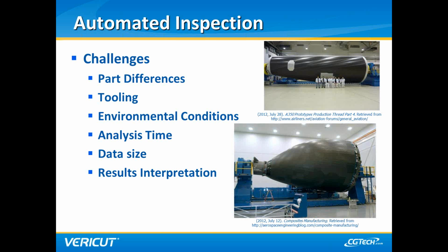And then the other one is results interpretation. So, how do you interpret results if you're looking at point clouds? What's one point versus the other point? Is something FOD, is it not FOD? How do you actually make that determination on the fly?